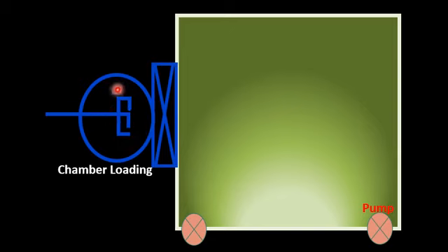If we want to deposit the precursor material from the chamber loading setup, the ring flips, and it is turned and switched inside the reaction chamber. In this way, the vacuum of the reactor does not break with the environment of the chamber loading setup.